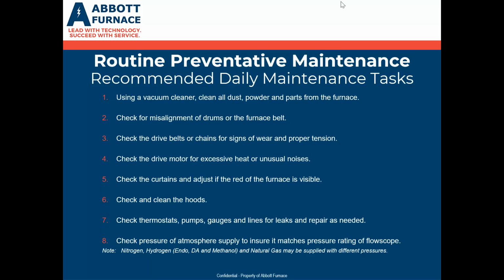to date and maintained. Of course, you want to clean and check all the hoods with all the atmosphere coming up through. Any buildup on that over time could cause you a fire in the hood or even in the stacks. And of course, you want to check the thermostats, the pumps and the gauges and other lines and leaks as repair is needed, because sometimes they will leak after running for a while.